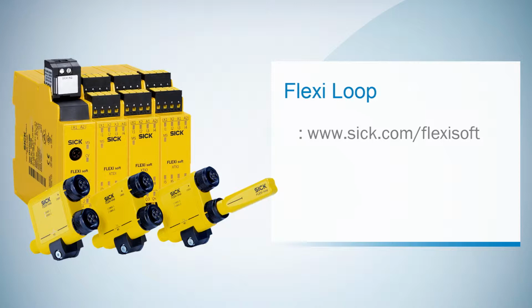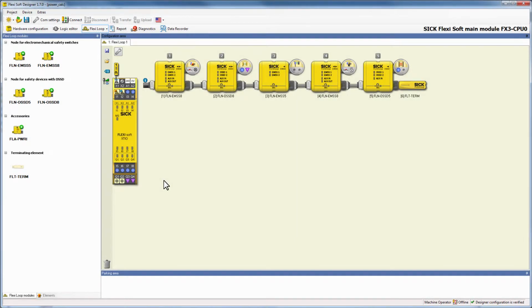sig.com/flexisoft. The power calculation tool helps you deciding if you need a power injector for your cascade by calculating the input voltage as well as the currents. Moreover, it helps you to determine where in your loop you can place the injector to achieve the best results considering your machine's circumstances.